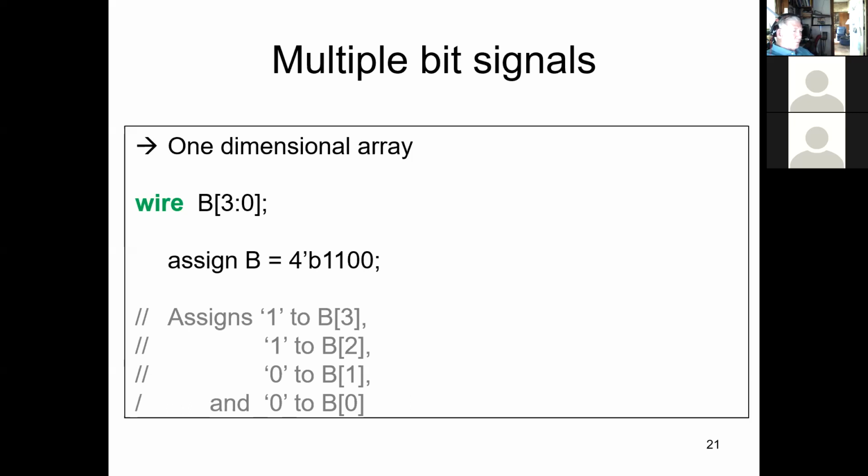Yeah, I guess you can use decimal. And then you put the numbers. If it's binary, then you can only put ones or zeros here. If it's hex, and the 4 is the number of bits, say this was 4 tick H, you could only have 1 hex digit here because you've only got 4 bits worth. And if you had 8 tick hex, you could have 2 hex digits. And if you specify more bits than the digits supply, it gets padded, and if you specify fewer, the higher order bits are going to be thrown away.